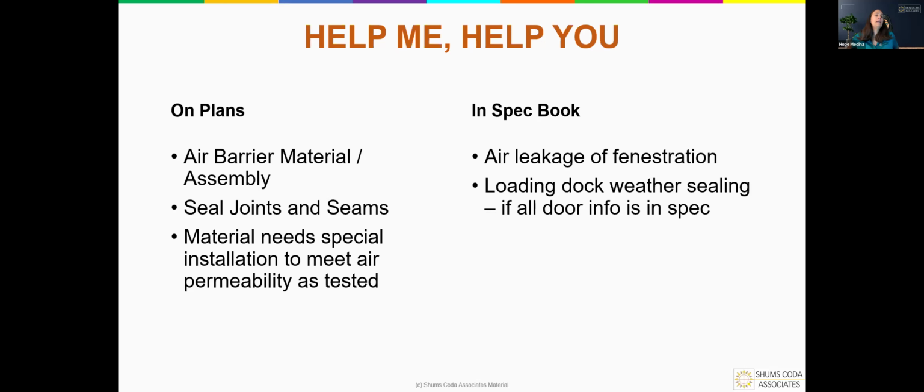Now, something I really want to have all of our architects and designers keep in mind, so that everybody loves to get your plans. There's always a question, what do I put on my plans? What do I place in the spec book? On your plans, because the testing requirements, as you can see, really got beefed up, and there's going to be a lot of situations, in my opinion, of what's about to come with all of the testing. You need to make sure that you tell me specifically what you are utilizing as your air barrier material or whatever the assembly is. Call that out on your plans.